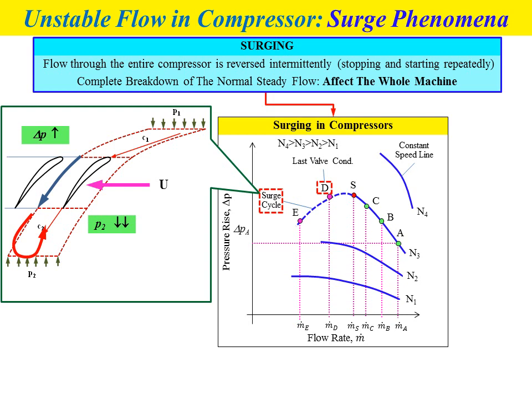When reverse flow occurs at the outlet of the compressor, the pressure P2 will reduce again, and because the compressor is set at a specific operation condition, the compressor will suck in more air in order to maintain the pressure rise or pressure ratio.